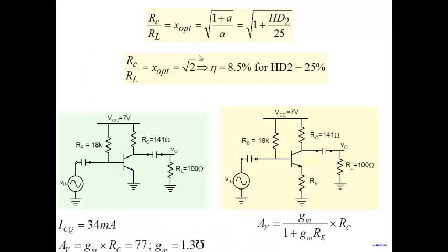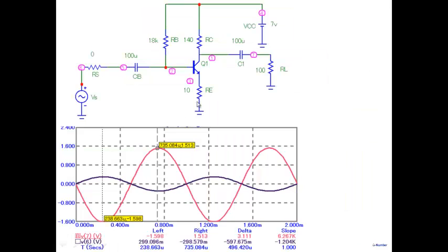Earlier, you remember all this design that you were doing, you were balancing both the saturation and the harmonic distortion part. So what happens is, because of this addition, now you find you're not able to go to 2 volt when you simulate. All that you can go is 1.5. As you try to go beyond 1.5, your transistor goes into saturation. I'm not showing you here.